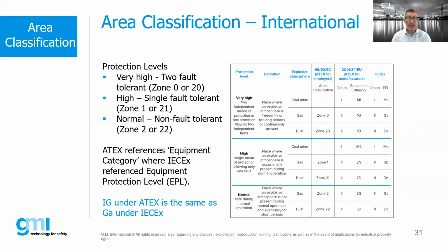One note, because I know a lot of you are potentially customers of GMI with regards to intrinsically safe barriers. There is what is called an IA barrier, an IB rating, and an IC. The GMI products are rated as IA for the most part, and these are considered highly fault tolerant, with some redundancy built in.